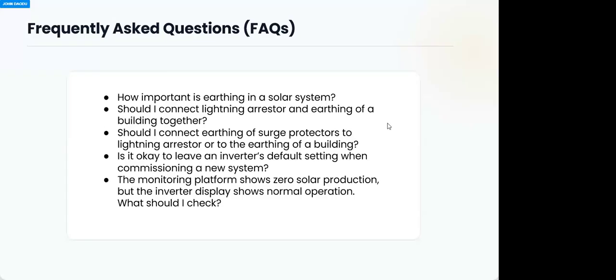This manufacturer said their own battery full point, which is bulk voltage, is 24, for instance. Another manufacturer will say his own bulk voltage is 25. Another one may say the bulk voltage of my own type of battery is 27 point something. So you need to go through their recommended specification and then go inside the battery charger, whether solar charge control MPPT or whatsoever, and adjust it to that,